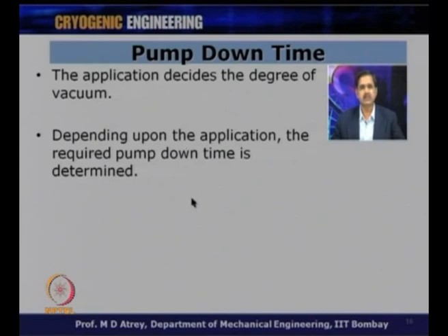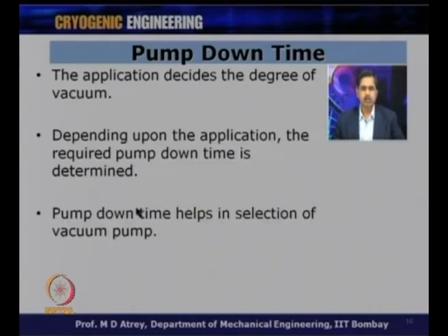It depends on how big my system is also, because the bigger the system, the more time it is going to take to pump down all the molecules. Alright. So, pump down time helps in the selection of the vacuum pump. So, I have to decide what is my volume to be sucked, what is my volume to be vacuumed. According to that, I will decide what my conductance should be and what my pump should be.